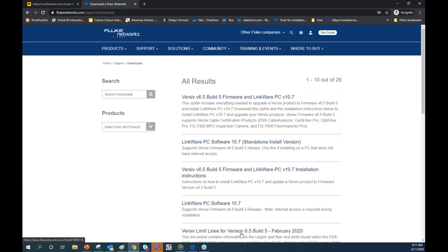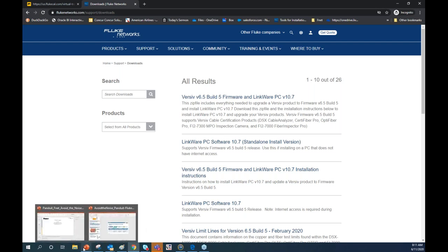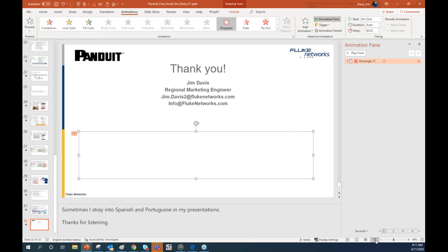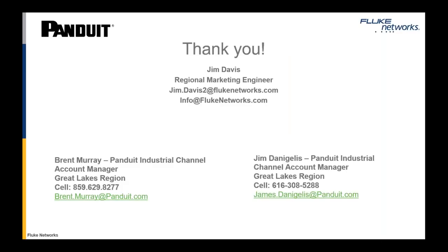Perfect. Okay, one more question here. Where would I use the zone enclosure that was shown? I believe, Mike Berg, this question is for you. So the zone enclosure that we were showing, that's an access layer switch solution. Any of the cube style industrial DIN rail mounted switches will fit in that enclosure. It's a universal design. It builds in the structured cabling into the installation, so it has a patch panel in there. It also accommodates the fiber coming in.